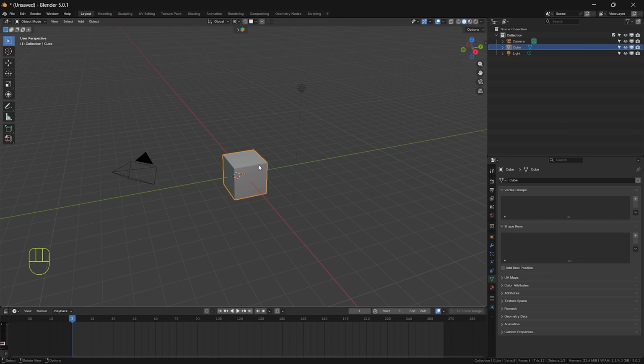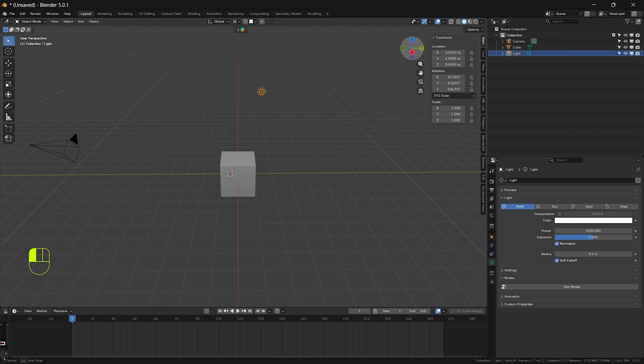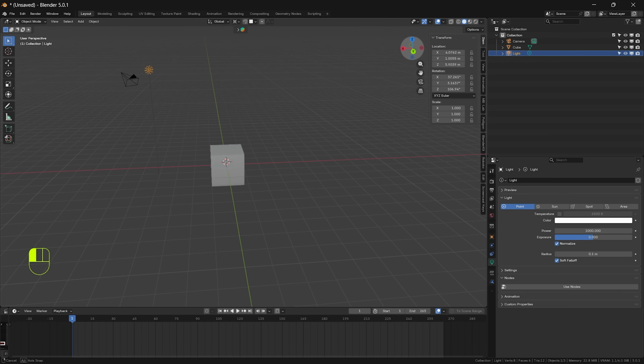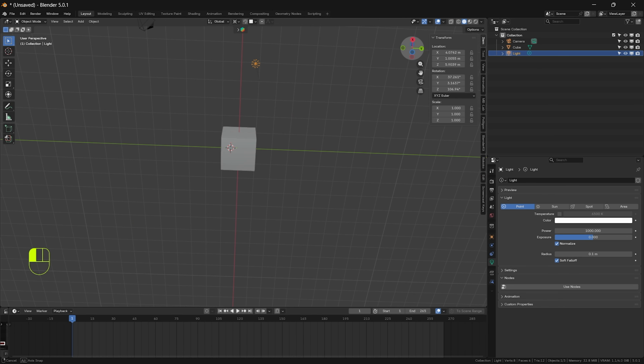By default, Blender gives us 3 objects: a cube, a camera, and a light. To look around them, direct your attention to this colorful RGB axis in the top corner. This is called the gizmo. It is used to rotate your view of the environment. Simply click and hold the left mouse button on the gizmo, then drag to orbit around your scene in any direction.